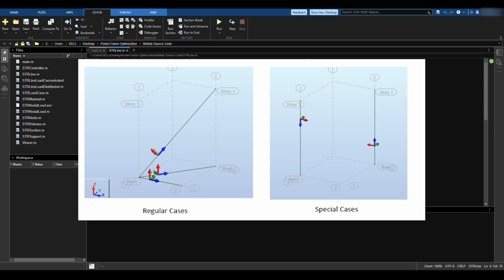The local y-axis is going to be a horizontal axis with orientation that shall be decided later. And the local z-axis is going to be the cross product of the x-axis and a horizontal y-axis. Finally, the y-axis is found by cross-producting the x and z-axis if need be, and this will be shown to you very soon.